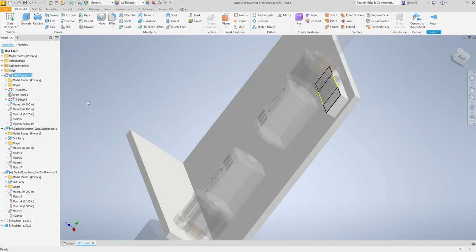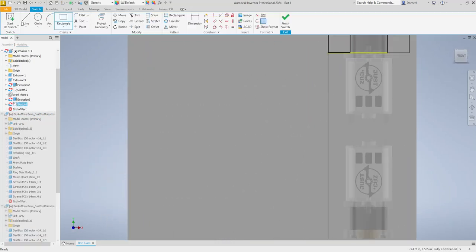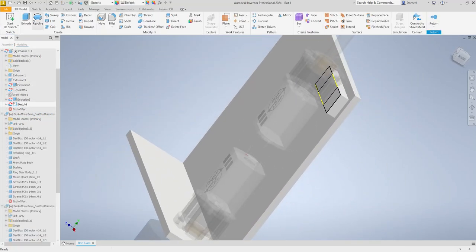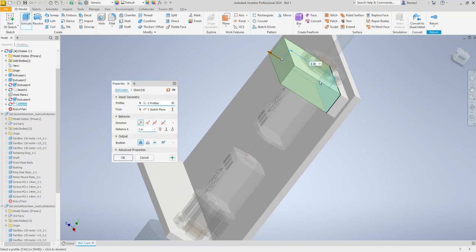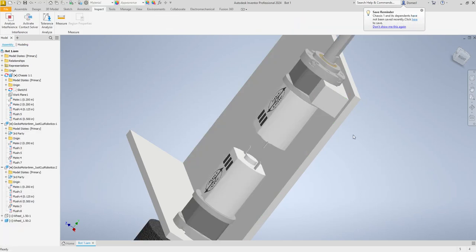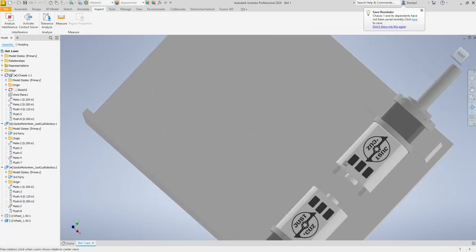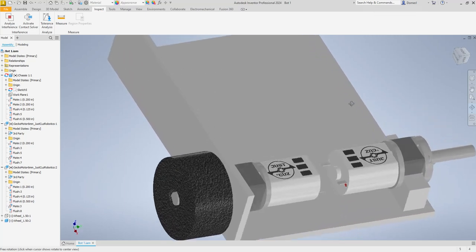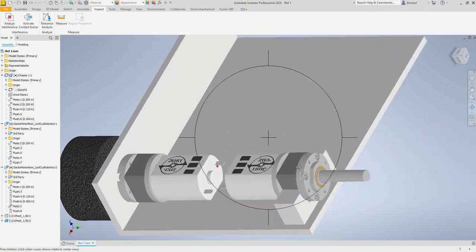So if I go back into my chassis, go back into that sketch. I don't need the sketch. We're going to extrude. Grab the right thing. Extrude that and that. 0.65 divided by 2. Return. And we have just drawn half of a motor mount that can help clamp around that motor.